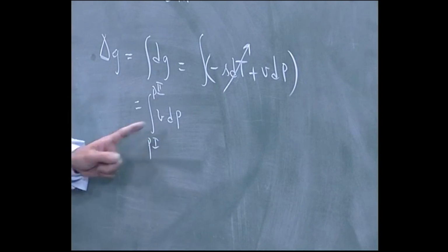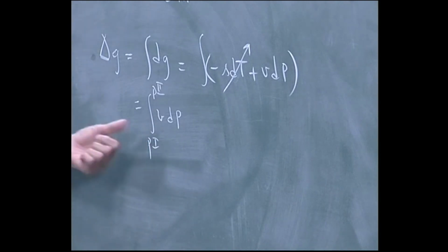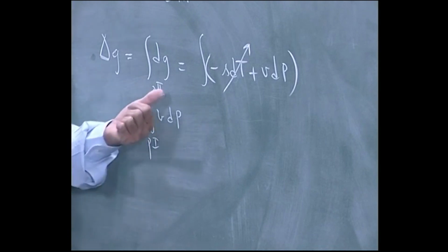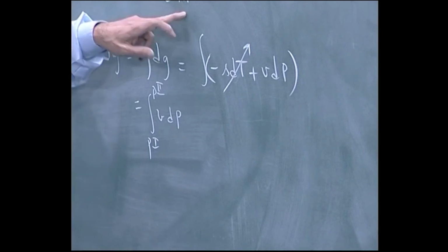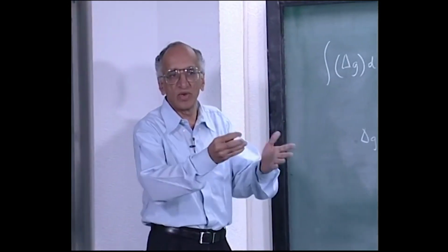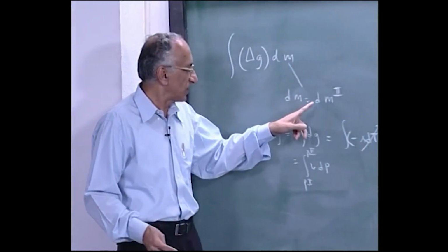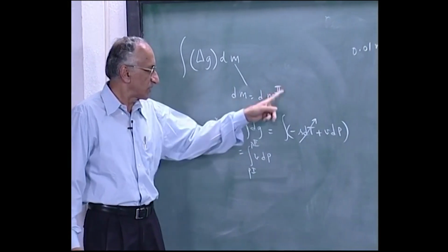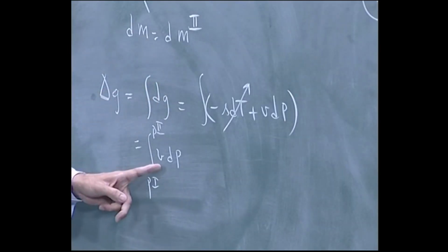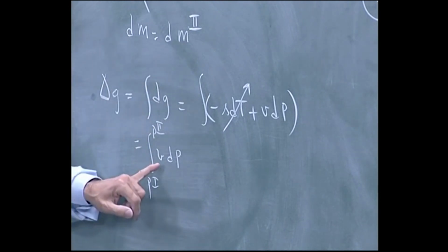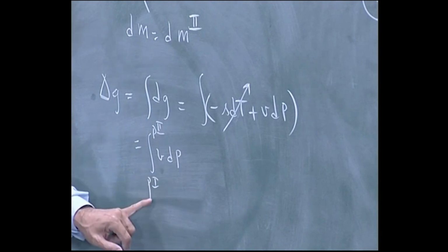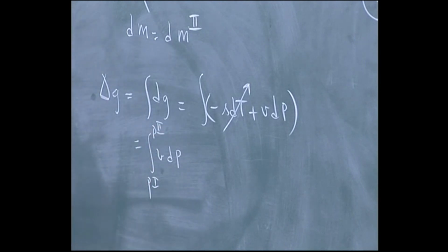At this stage you have to do a numerical calculation, because in the chart you will have to start with P1 to P2 at any given mass. So when the mass is equal to m2, which will go from 0 all the way to the final total mass that was initially in the system, at every mass you have to calculate that is you assume M2, start from 0, make small increments, at every point you have to know V from P1 to P2, that is you go along the isothermal line from P1 to P2.